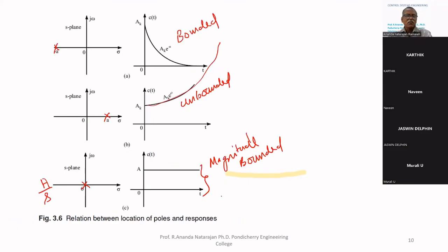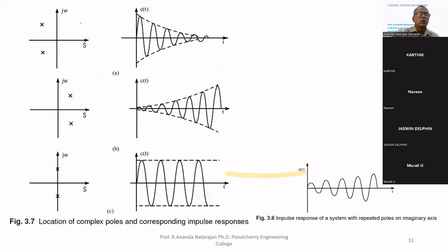These are all real poles, with no oscillation. If we take complex poles, 2 poles, a second order system, on the left hand side, it oscillates but finally, for impulse input, not step, it comes to rest. Impulse input means giving a punch, after which it is initially at rest.